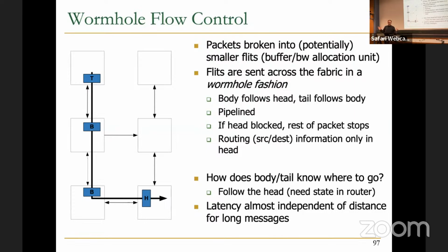So that's why, especially for long packets, the number of hops is not really an important metric for the latency of that packet, because it only defines the latency of the header flit. Other flits are pipelined and they will arrive at the destination every cycle. Is that clear? Good.